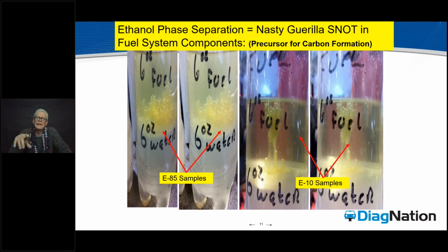And what ends up happening here is that at 5 days, we have this growth right here. Look at the growth in the E85 because of the alcohols involved, stripping that fuel even faster. This is the reason, the visual reason, why we can understand why ethanols have to be blended at the terminal level and cannot be put in at refinery, because if they were, the fuel would be going to this before it ever came out of the mobile station tank and into the car. No bueno, right? So this is what we're after. Now, this is going to create probably 80% or more of the depositing that's going on in that vehicle.